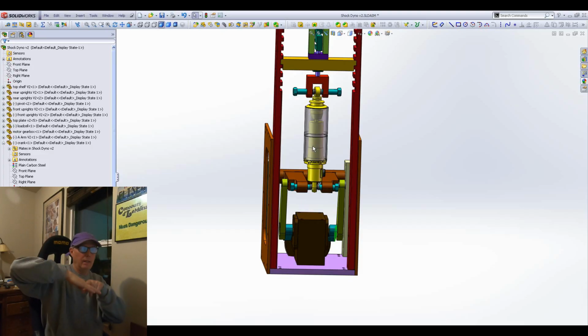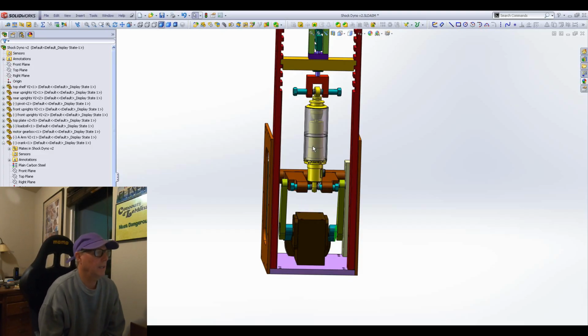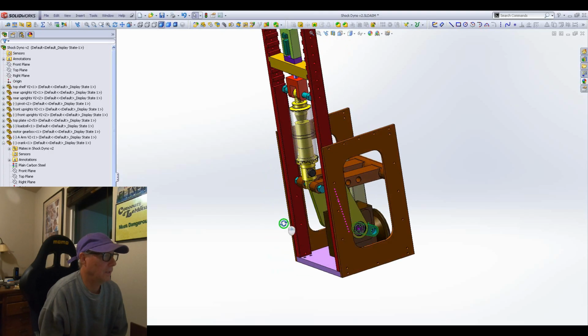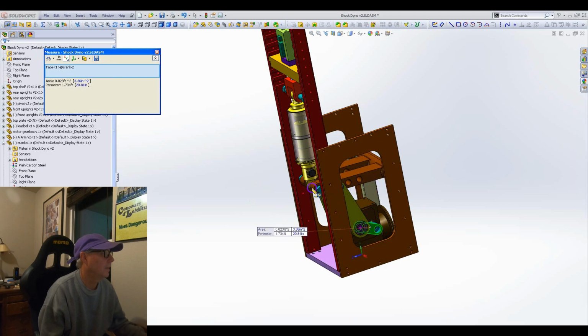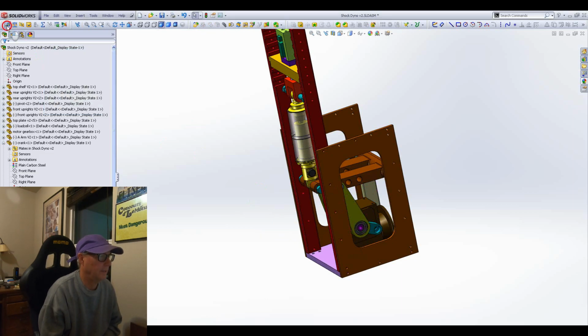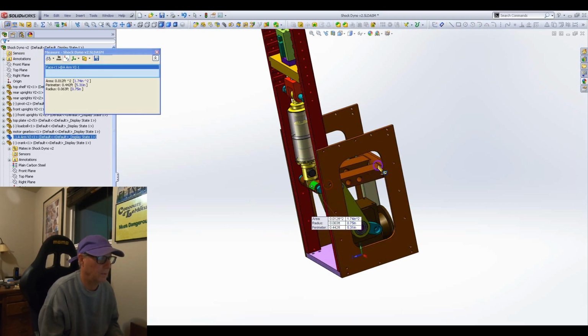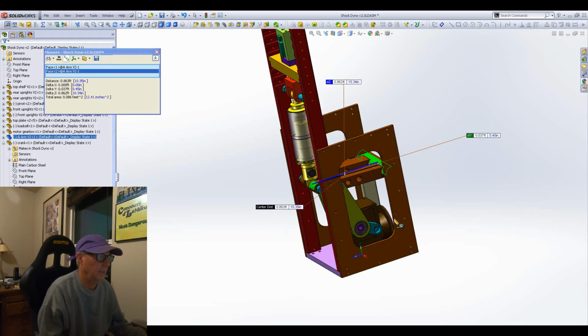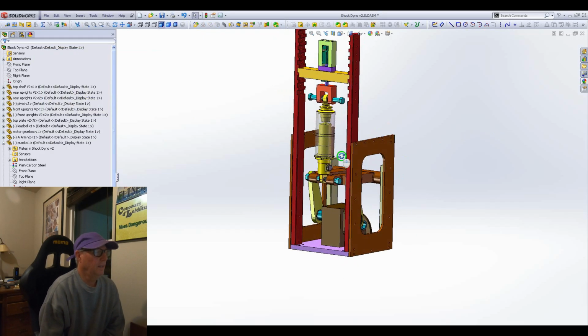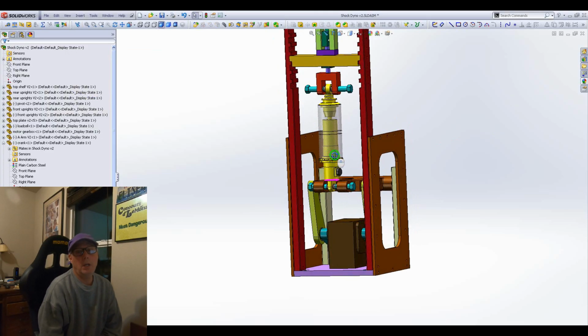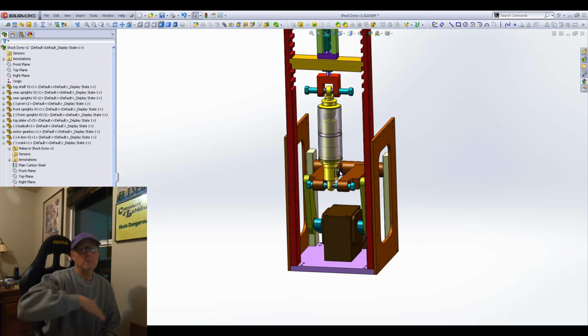It's not a huge amount. The A-arm's, I don't know, 10 inches long or something. I forget. Let's measure it. We've got the technology, and I drew this months ago, so it's 10.34 inches. So it's fairly long, but when you get to a high travel, it's going to put quite a bit of side load on it.